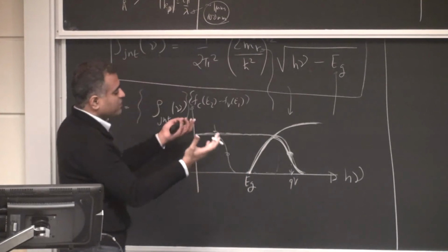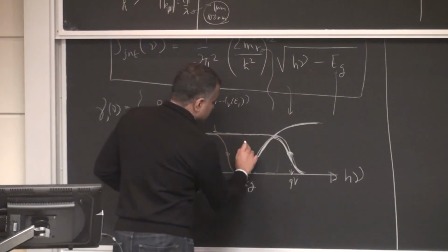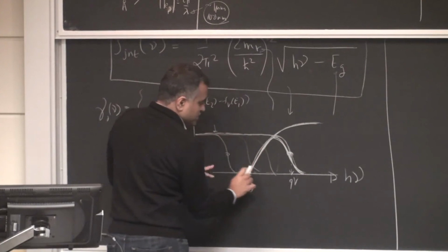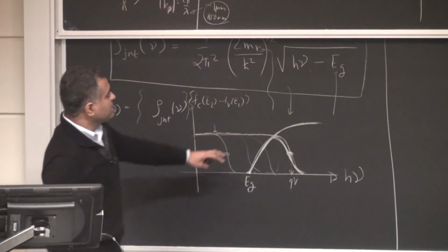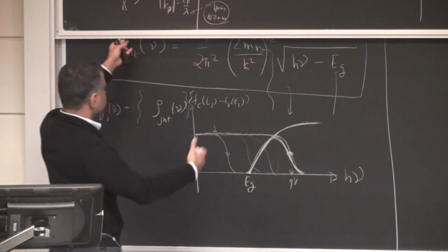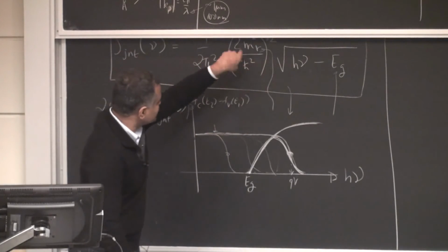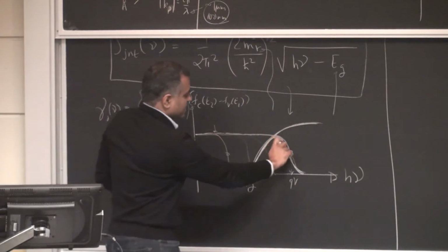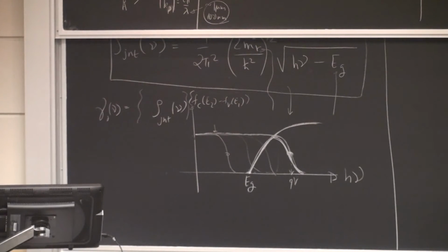And that's a photodetector. It absorbs photons rather than emits. As you get closer, when you apply more and more voltage, I'm going to push this out, and finally you'll have a gain spectrum, something like that. So the gain spectrum of a semiconductor, if it's three-dimensional, is really very similar to the joint density of states with a little Fermi tail acting on it as well. So that's the main point we wanted to stress first.